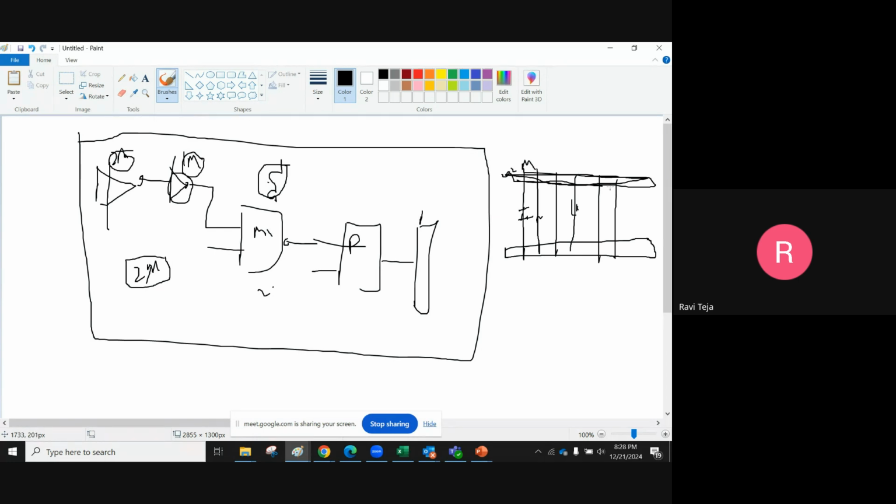Here I am saving a lot of area. Imagine if I make one thing in 1 micron and another in 2 micron: you are not only wasting area, you are also increasing routing resistance, capacitance, and parasitics from the inverter to the next cell.